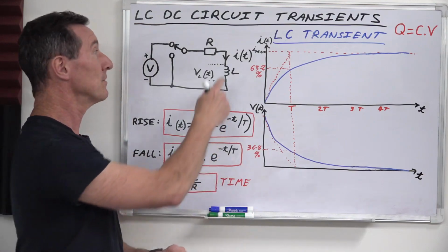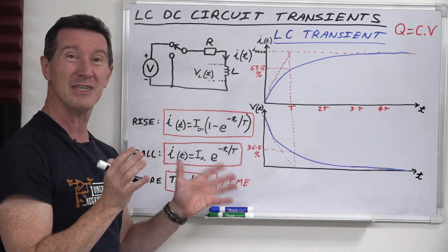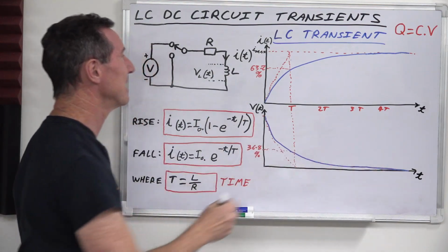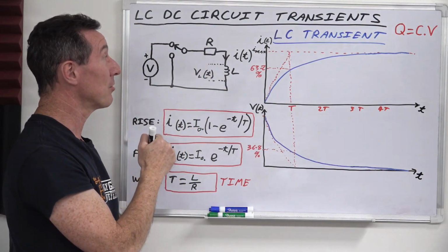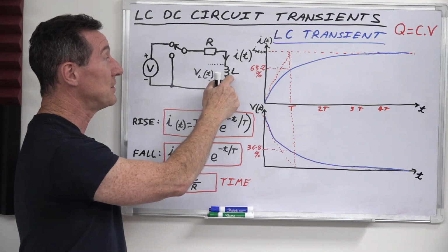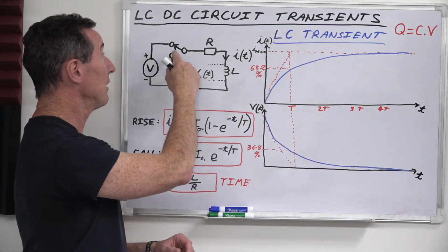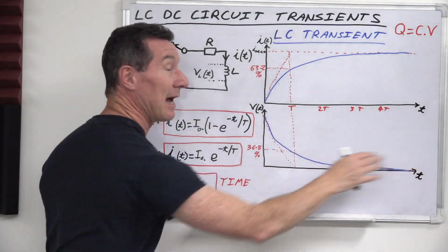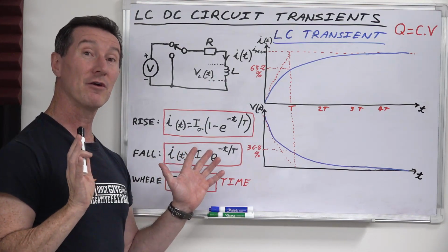It has 0 resistance in the coil, but of course all practical inductors have a series DC resistance, so it's not going to be precisely 0 like this. You'll have to use your voltage divider, which we've looked at in previous videos, and then you'll have R in series with the DC resistance of the coil, and that's what you're left with. If you leave that switch on long enough, it'll eventually decay down to whatever the DC resistance of that coil is. But in theory, 0.